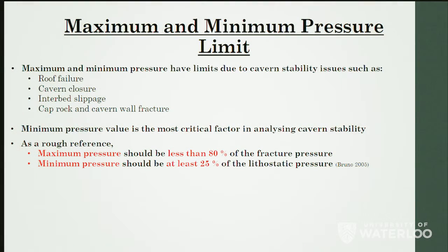The third is interbed slippage. If we have non-salt interbeds in the salt cavern, and if we lower the pressure in the cavern, the salt will start to creep, but the non-salt interbeds will not respond to creep. So there will be a stress difference between the salt beds and the non-salt interbeds. This can cause interbed slippage.